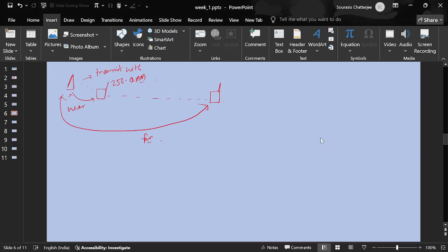Okay. The base station doesn't know about this channel change. The user is supposed to report back the MCS to the base station, saying that my SNR has dropped, so now please transmit with QPSK or BPSK. That information hasn't reached the base station yet. The base station is still transmitting with 256 QAM. So that's the scenario I'm referring to.